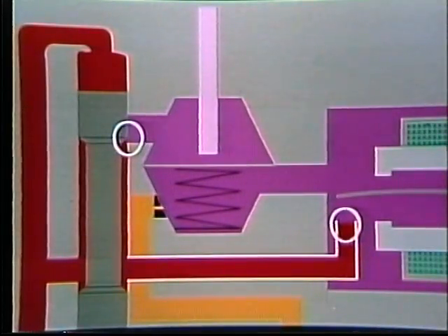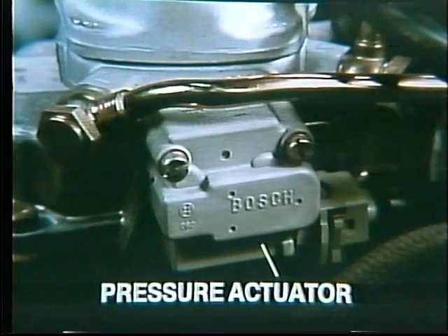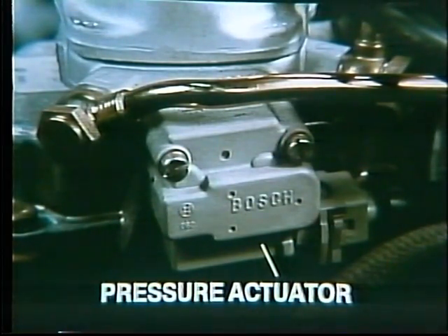Pressure drop of injected fuel at the slits is controlled by pressure drop of actuator fuel. The pressure drops in the circles are related. Pressure drop at the slits can be changed by changing pressure drop at the inlet to the actuator. Let's look at the next step to see how the pressure actuator, for any given airflow and its related slit opening, compensates mixture by changing flow of injected fuel.